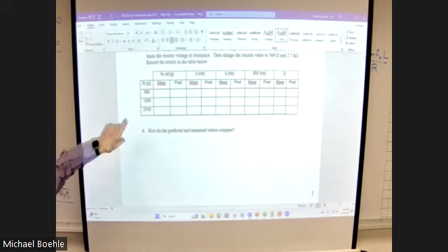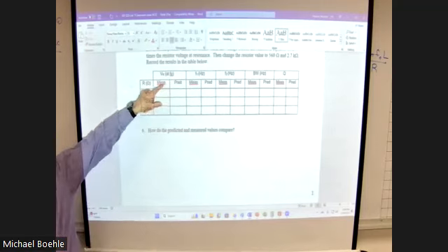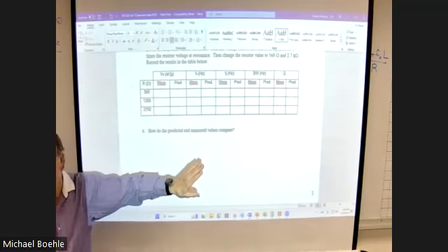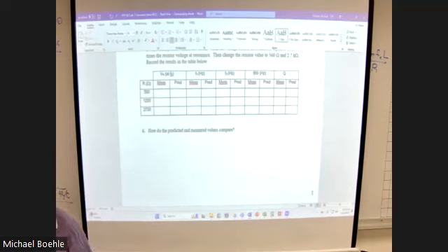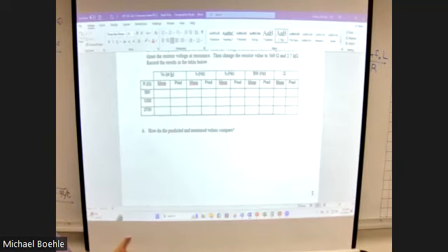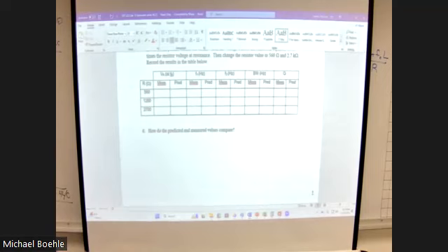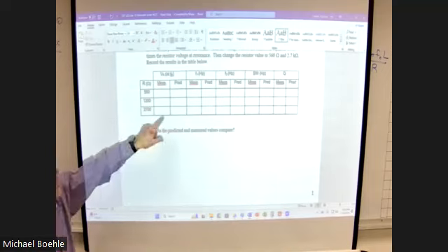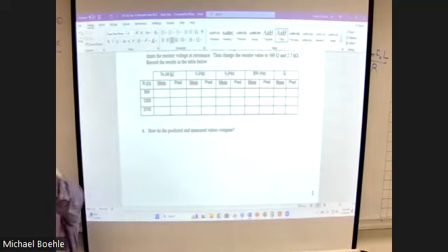Well, you take whatever your voltage is at resonance across the resistor, 3.6 volts peak to peak, 3.55, whatever it is, you multiply it by 0.707. Because that is what you're going to see at the cutoff frequencies. So you're going to figure out what that voltage is.